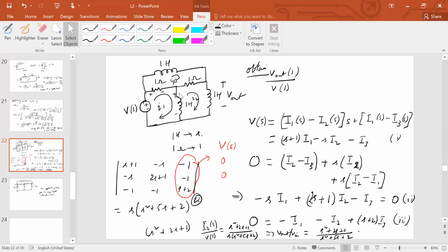But on the other hand, if I had this one, of course, even then you can sort of find out the equivalent impedance, but it's not a very good idea. If you had say some element in parallel with this, okay, you could have considered an additional loop here, all right, to accommodate that. So if instead of having it being in series, if this inductance of 1 Henry, there was another inductance of 1 Henry in parallel with this 1 ohm, you could have considered that as an additional loop. Very simple equation of the loop though, but anyway, you could have considered that, right?